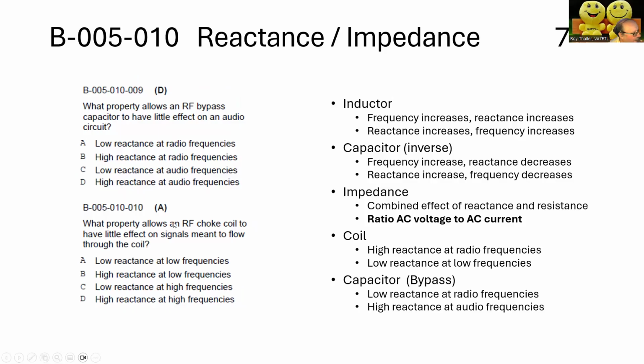What property allows an RF choke to have little effect on signals meant to flow through the coil? So here again, remember, low reactance at low frequency. So A is the correct answer.